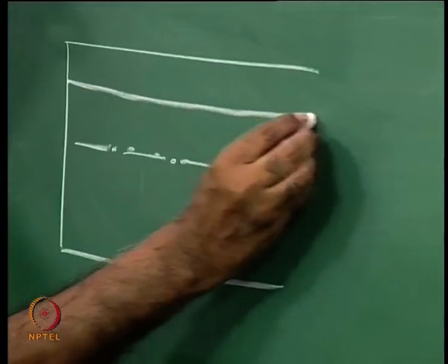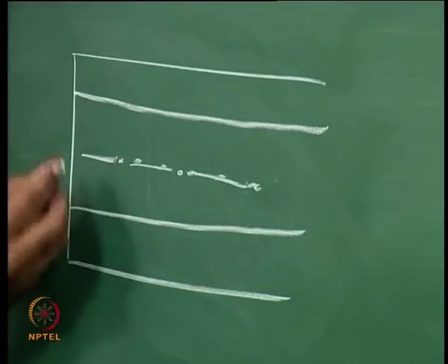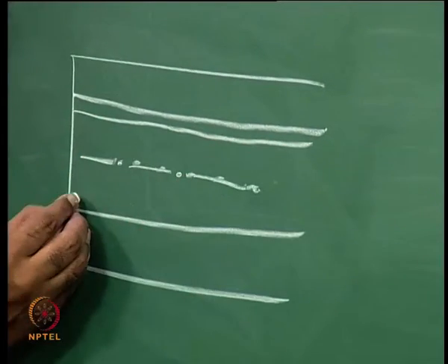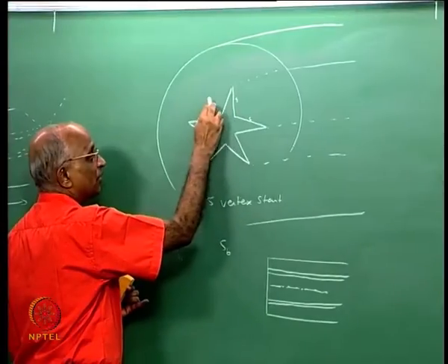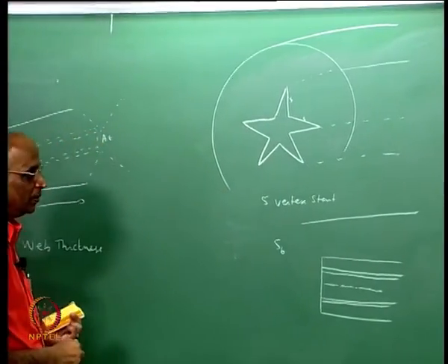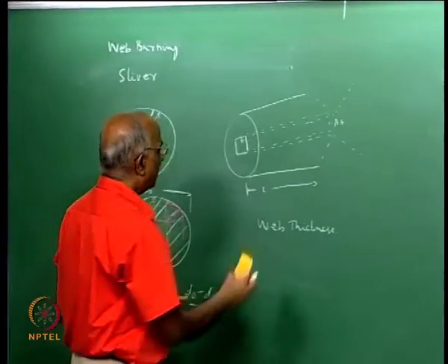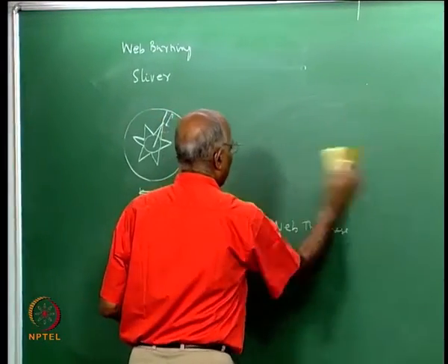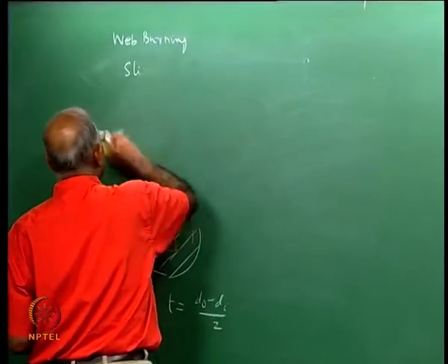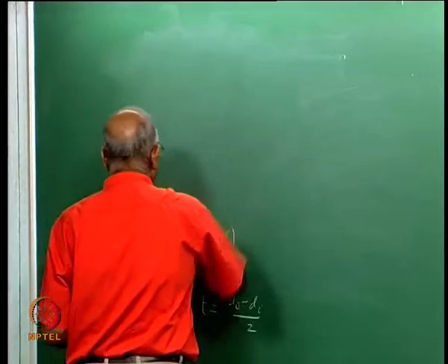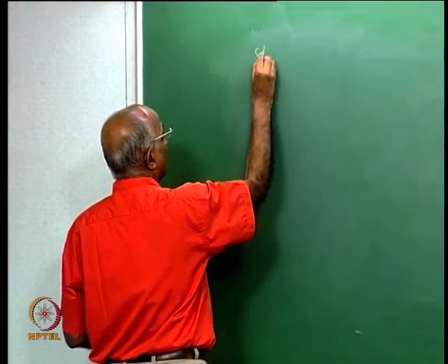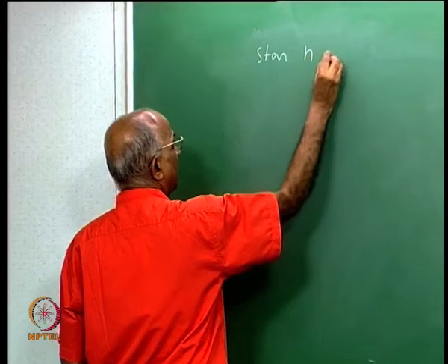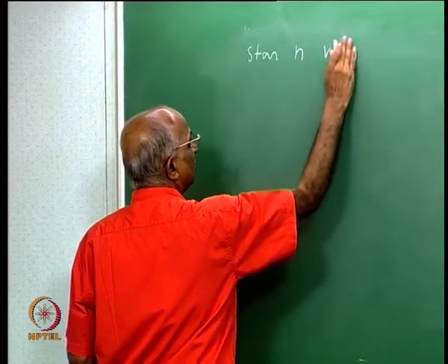Corresponding to one vertex I get a line over here which should be dotted, I get another line over here corresponding to the other vertex. I am interested how the surface keeps evolving. Now you could tell me, if I were to now calculate the burning surface area initially, all what I say is, well, let me have a star grain with n vertices.